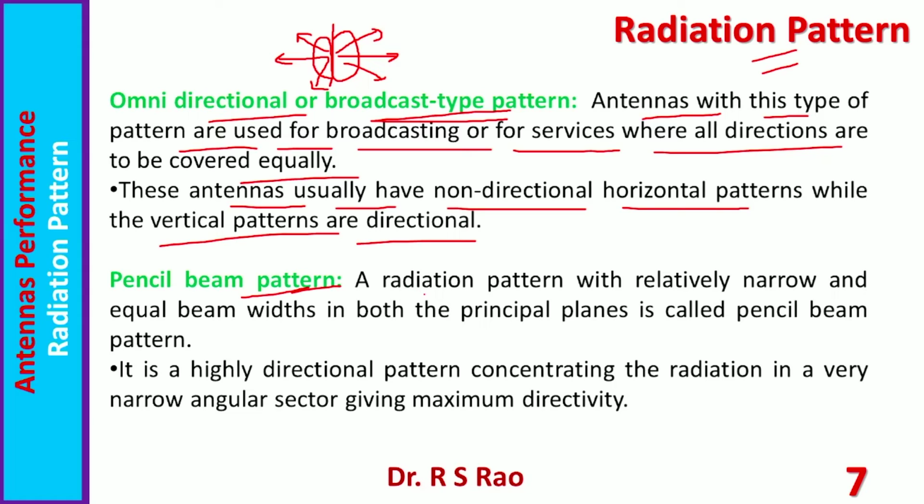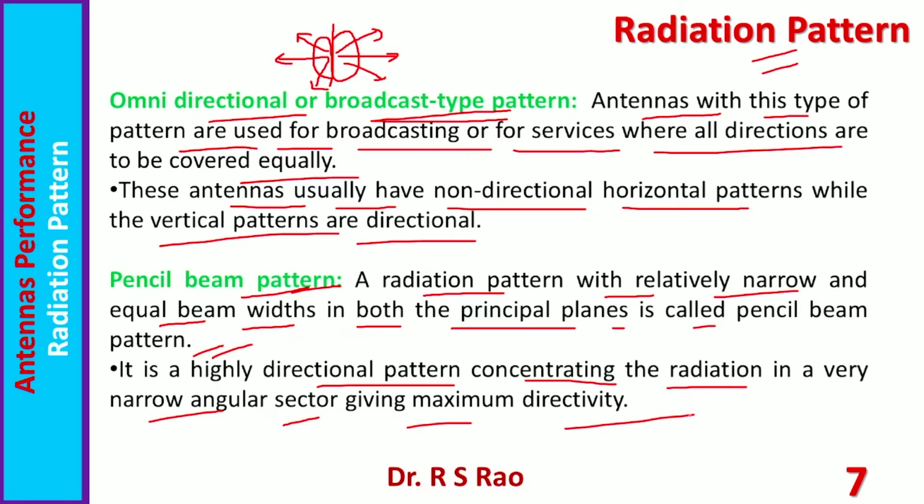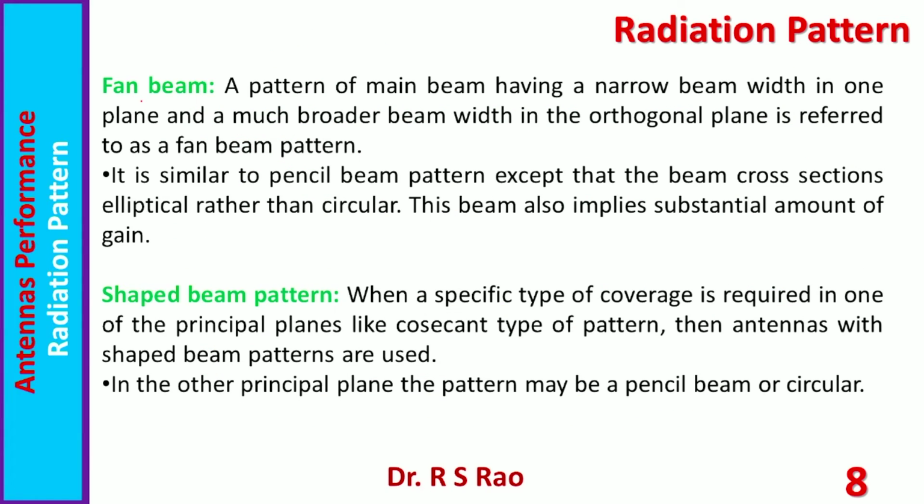Pencil beam pattern: a radiation pattern with relatively narrow and equal beam widths in both the principal planes is called pencil beam pattern. It is a highly directional pattern concentrating the radiation in a very narrow angular sector, giving a maximum directivity. Another shape of a pattern we encounter frequently is a fan beam.